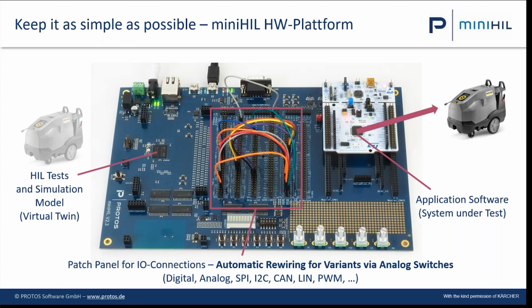It's not as hard as it sounds, but that's the biggest part of hardware in the loop testing, is always to build the environment simulation to make your application believe it actually lives in reality, and it controls a real motor, a real battery, and a real sensor, things like that. So on that level, we connect the typical low-level IOs like digital, analog, all the low-level bus systems, SPI, I2C, CAN, LIN, field bus systems, and so on. So that's how we do the hardware approach here.